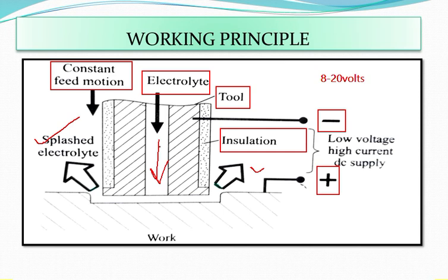Next, the gap is of the order. You are maintaining a certain gap, isn't it? You can see a certain gap has been there. Then what should be the distance of the gap? So the gap distance has to be maintained between 0.1 to 0.2 millimeter.